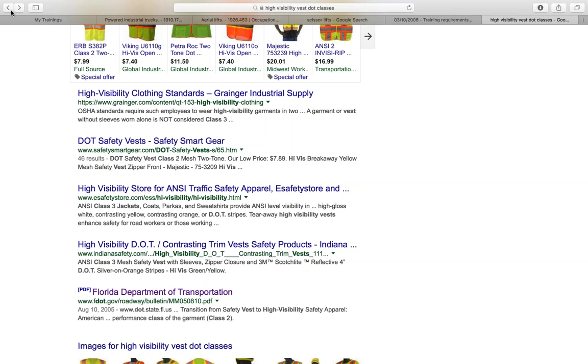Advising employees if there are puddles of any type of fluids on the ground, especially fluids that are an unusual color or odor. We have to report anything that's not on the job work order or on the job training already. We need to make sure we report, because it may be a new hazard that wasn't identified during the job hazard analysis. Also, any fluid seeping out of the ground, unusual foul odors, right? Unmarked barrels or tanks, they may be buried and may come up in the ground during the excavation. So we need to make sure that we watch out for that.